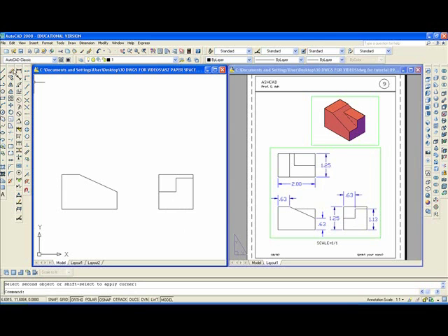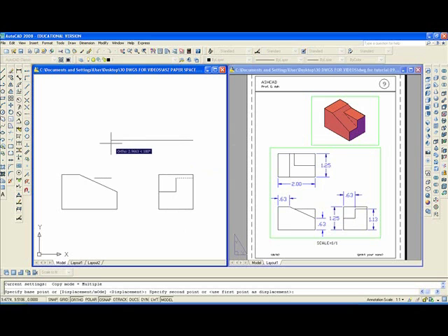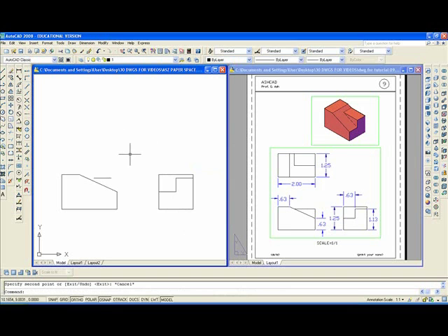but now we have to project over. So I'm going to copy this, drag it over here like so, escape. I'll do the fillet command here and extend EX, enter, to this line, enter, that line.